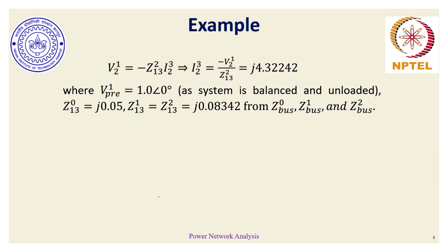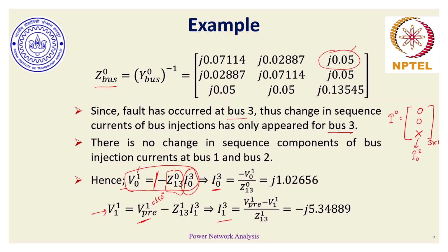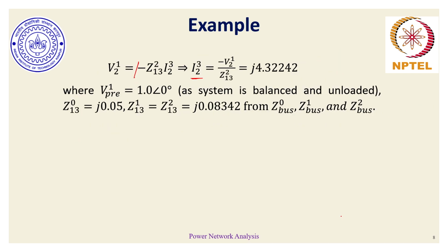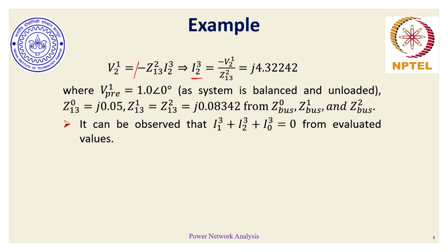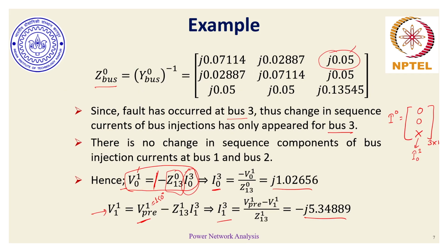And similarly for V2, which is the negative sequence network, we have a passive network, so we can find I23, I13 and I03. Now when we look at these three currents, what appears is that the sum of these currents is 0. Now in which type of fault was the sum of these three currents 0? Definitely there is an involvement of zero sequence current because the zero sequence component is not 0. So it is definitely going to be a ground fault.